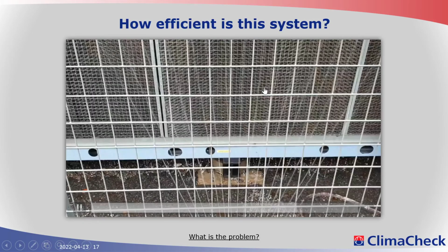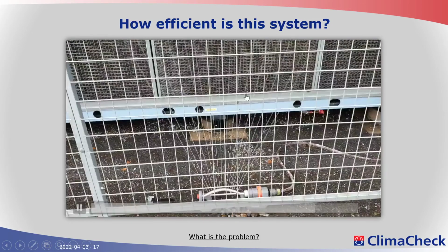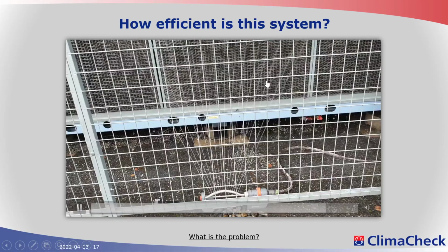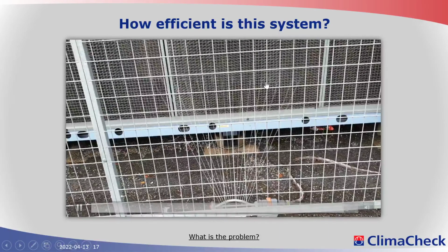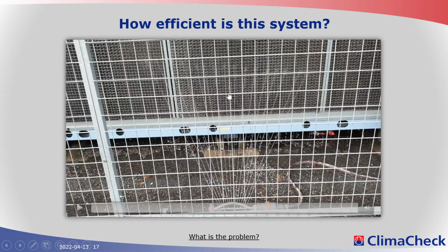and you're destroying your condenser that was not functioning well from the beginning. This is absolutely not acceptable. There is no system designed for having a water sprinkler required when it's 18 degrees outside. And if your system is not designed to operate at the conditions you're operating, you should question it rather than trying to fix the system short term with a water sprinkler.